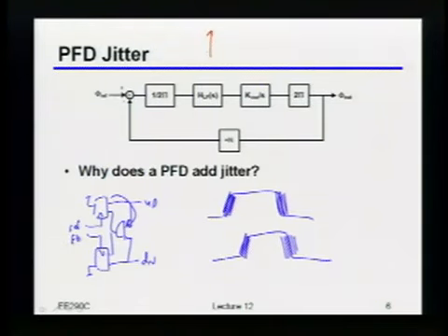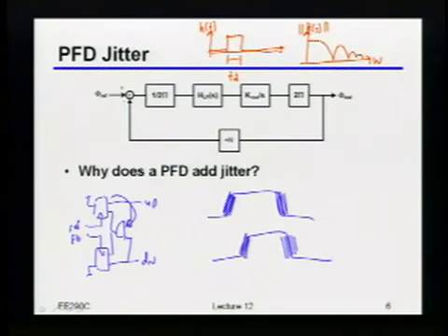Okay, so if in time my impulse response is something like this, just some nominal box or some nominal delay, then in the frequency domain, if I look at the magnitude of that transfer function versus frequency, what you get is something that looks like this. Okay, now this first null here is just sitting at, and I should be more precise, 2 pi over TP, in radians per second.